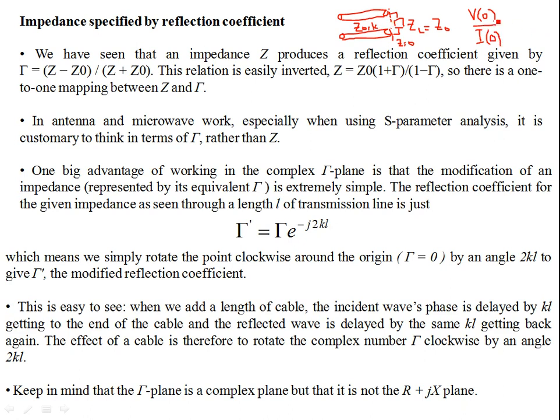Okay, so at the point we are talking of, at Z equal to 0, at the point where the load is attached, if this is equal to Z naught, if it matches with the characteristic impedance of the transmission line, then there is no reflection. So all the power is transmitted down the line to the load. There is no problem of reflection. But if ZL is not equal to Z naught, and V of 0 divided by I of 0 is different, it's some arbitrary load ZL, let's say it's not equal to Z naught, then we have reflection.